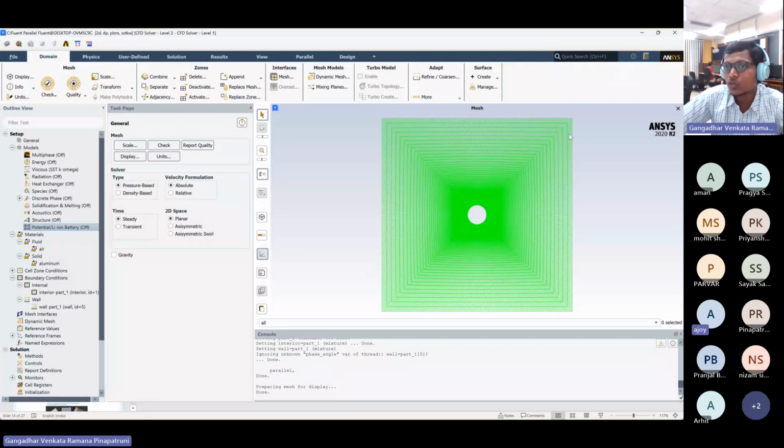And I need to tell the software that whatever fluid is entering from here, make that fluid exit from this surface. From this surface, the fluid will get out of the computational domain. And I also need to tell my software this is my surface, or this is my body, so that you don't allow the fluid to pass through this body. All these conditions I need to give to my software.